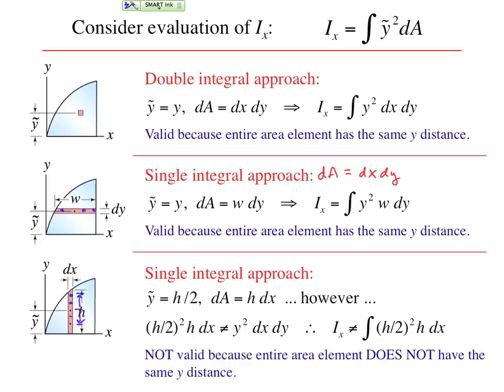But when the weighting of the position is nonlinear, in our case squared, this is not the case. The average of a squared position is not the same as the square of an average position. So we are not permitted to extend our practices for centroid calculations directly to those for area moment calculations.